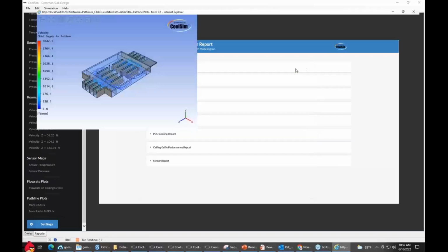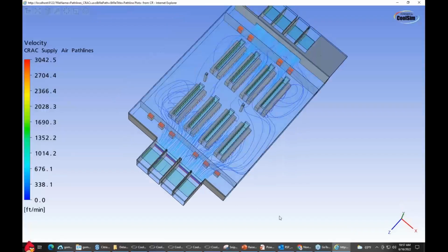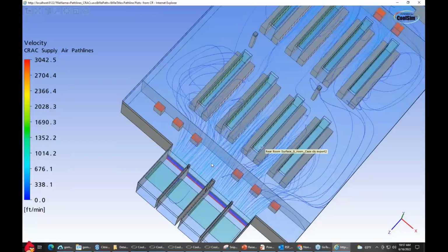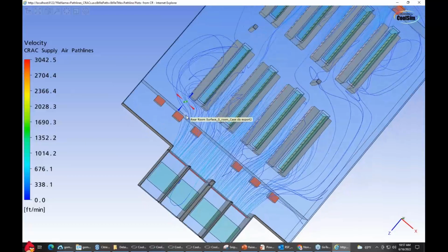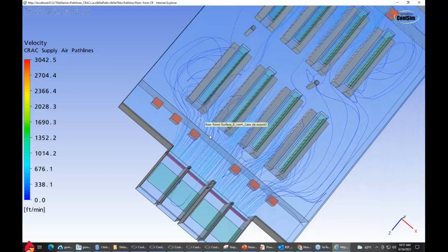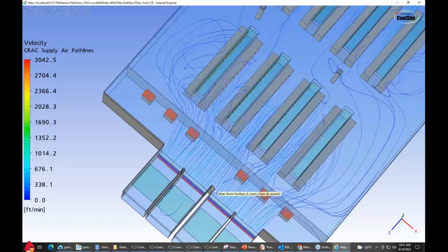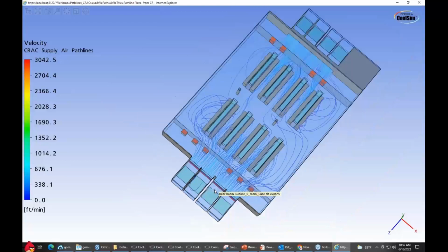And I see them coming up on the top of the hour, but look, most of that air is going into the center here, right where those air handlers are. And by the time it gets over here, there's not a whole lot left. So the servers over here aren't getting enough, and this is in the case where they're all on. Now, if this were a supply plane I'm staring at, that would all unify and I could use the tiles. It's essentially a manifold. The raised floor becomes a manifold from which you can modulate the amount of air coming out of it.